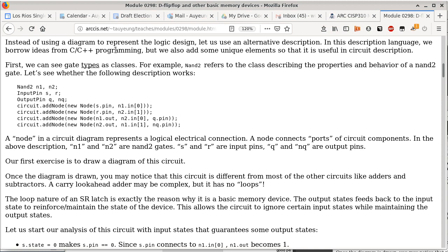And that's why it needs to be resettable, so that when you power up a computer, a reset line that is global to the entire motherboard will tell every single component, okay, you and you and you and you, everybody, reset to whatever the reset state is supposed to be. Now, normally we say the reset state is 0, but that may not be the case for certain devices. For certain devices, the reset state may be a 1. That's okay too, as long as it is deterministic and we know that it is safe for that device. It doesn't have to be 0. So does that answer your question?